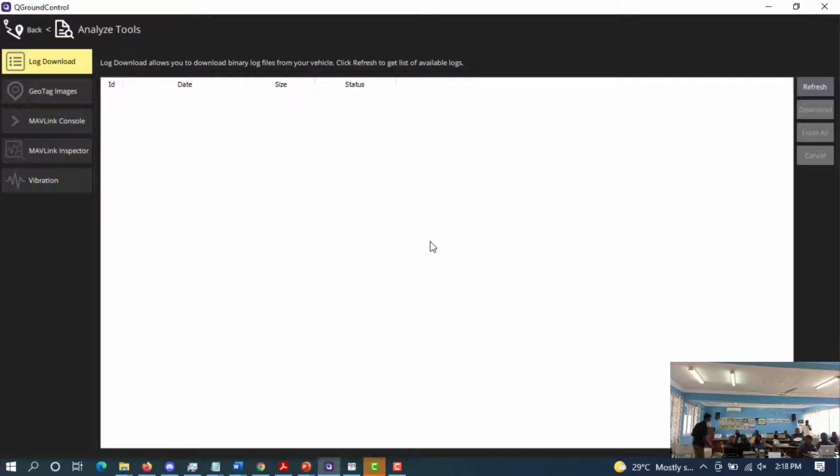But the thing is that if I don't create a platform so that I share my problem, we solve it, and maybe somebody also shares the problem, how do we strengthen the knowledge base? And that was how we solved it. They just moved the drone to another location because we were having magnetic interference. It was this Mission Planner MAVLink Inspector that was outputting that error. I didn't understand the error. I copied the error and put it on Google. Google didn't give me any result.